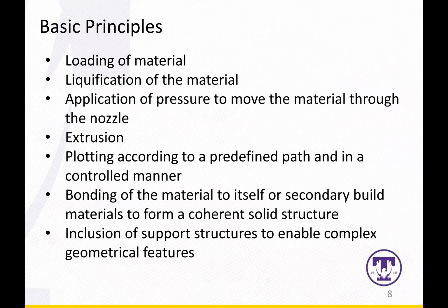And another thing is the support materials, right? So support structures, actually. For those complex geometry features such as overhanging and undercutting and so forth, in one word, if the geometric feature cannot support itself, due to the printing direction being upwards against gravity, there are some geometric features that cannot support themselves.